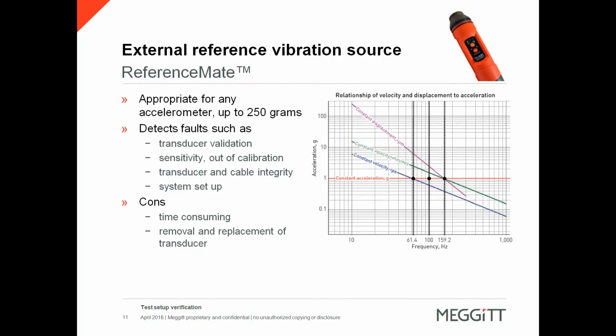The accelerometer is mounted onto the shaker and excited to a known 1G value and a selected frequency. This directly verifies the accelerometer integrity and the system setup. You want a quick check of a calibration and all connection from transducers to DAC. Well, simply put, a known vibration in, get an expected reading out, simple like that.